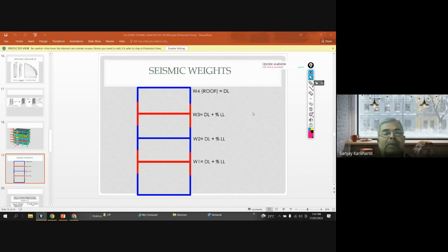No, the floor will be subjected to the load on that floor only. Then the above floor load is transferred at that floor level on beams, and from beams on columns, and from columns on lower columns, right? So that is a different thing.